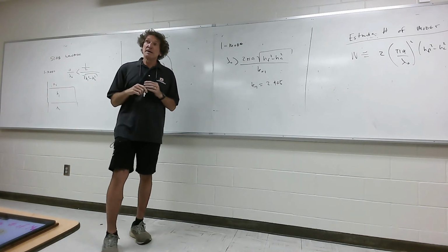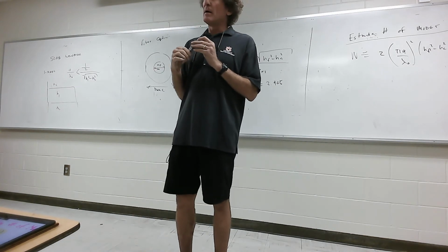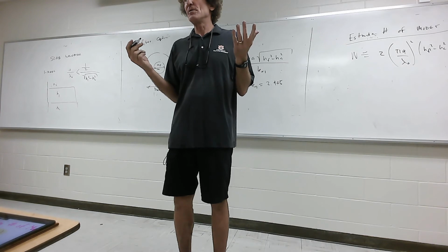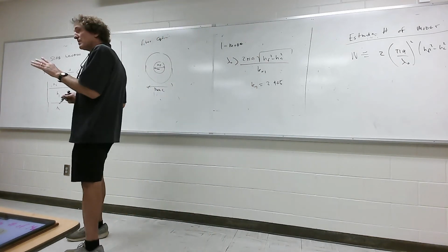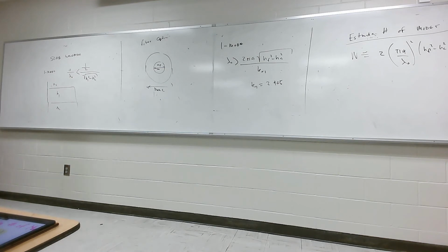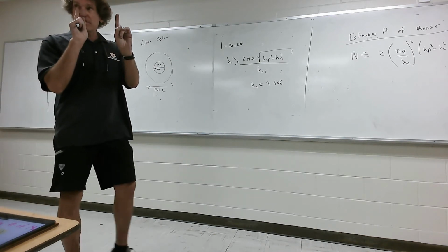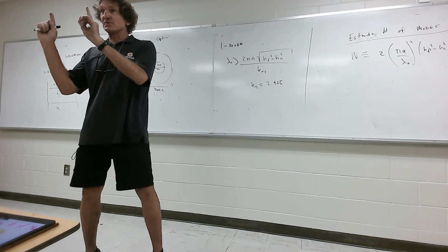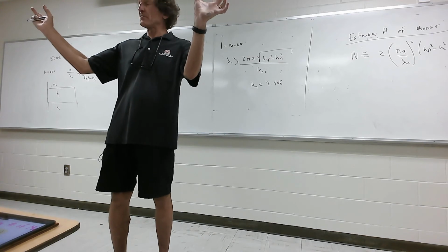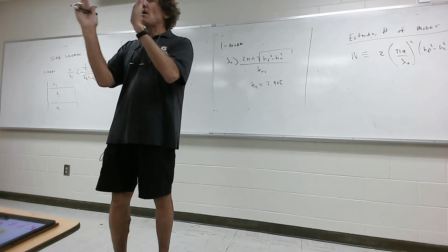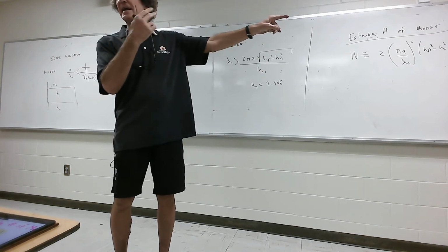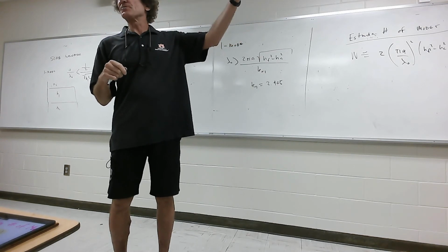You can't tell. Yeah. So you can't run multi-mode fiber with long distances? Well, you could, but you garble everything, because when you're dealing with this kind of stuff, there's all sorts of simulations we could do. But the real thing is, when you send pulses, even if it's single mode, they'll be spreading. When you send a packet of photons, as it moves down, fiber optic disperses. But with multi-mode, it disperses really fast. If you send your first packet here, if you froze time, second packet's here. Well, as they're broadening, there comes a point where they overlap, and your photodetector can't tell one from the other. It's just a continual string.